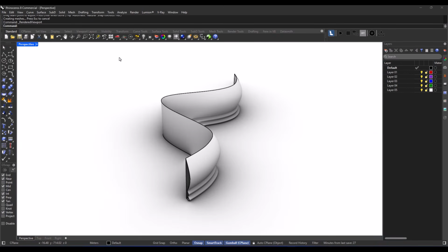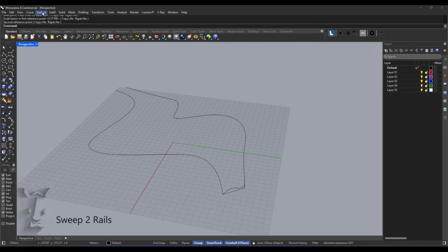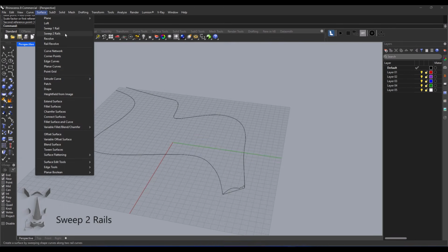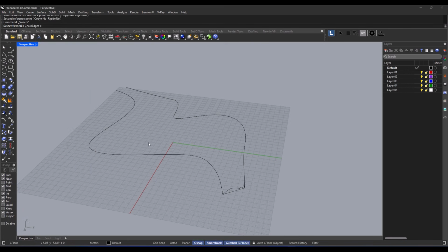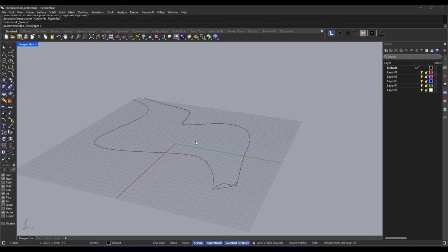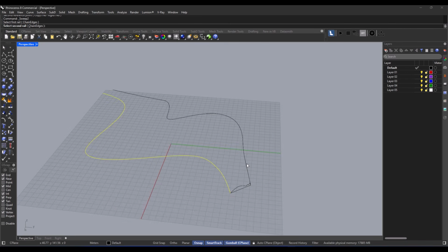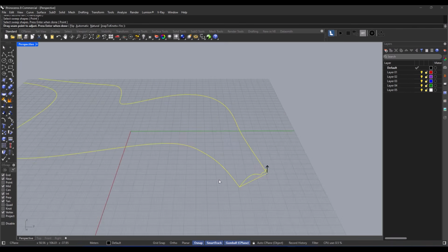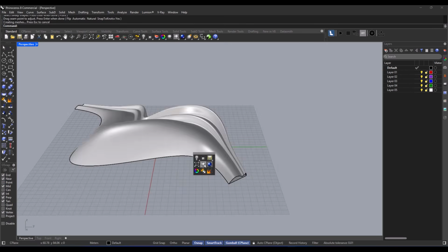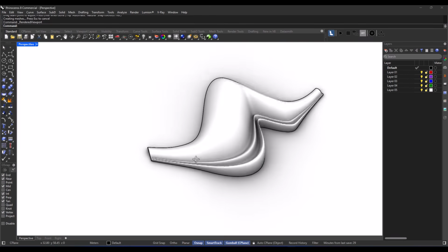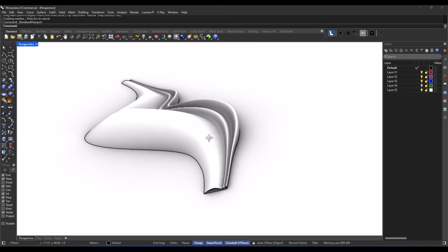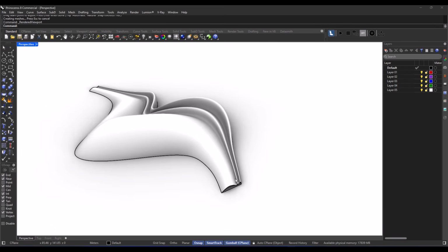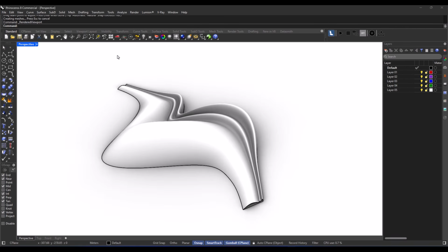All right, let's talk about sweep 2. You're going to fit a surface through profile curves that define the shape, and you need 2 curves that set the edges of the surface. Okay, so here's what you do. First, select those 2 curves, they're your rails. Then you grab the cross-section curves in the order that the surface is going to pass through them. Just make sure the open curves are near the same ends. And if you're dealing with closed curves, you have to adjust the seams really carefully. It's all about getting that perfect fit.